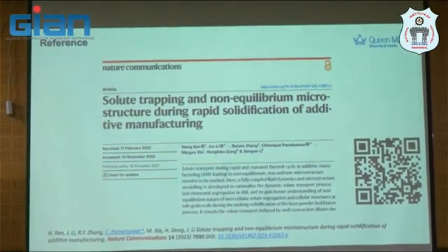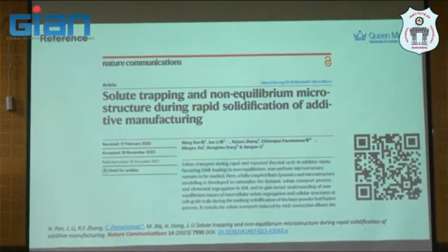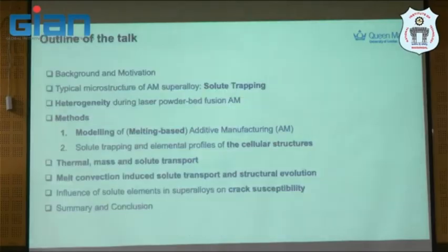How we try to understand this is to use the multi-scale, multi-physics model to give insight into this phenomenon, what happened, especially for nickel-based superalloy, and an understanding of the non-equilibrium nature of this intercellular solute segregation. That means we try to resolve how this dislocation or cellular structure profile happens as well. So it's a bit scientific, and I hope you enjoy it somehow.